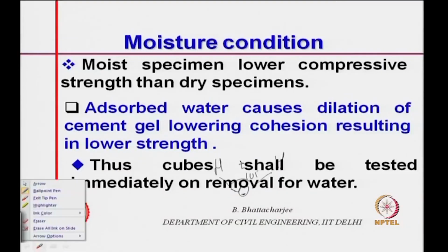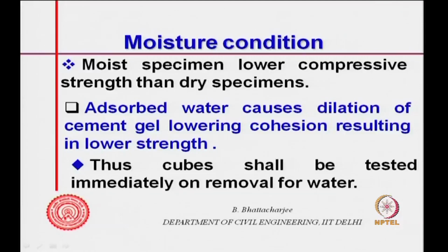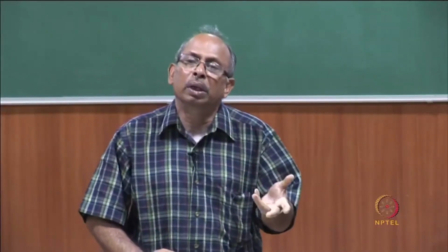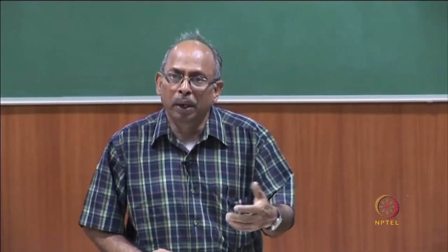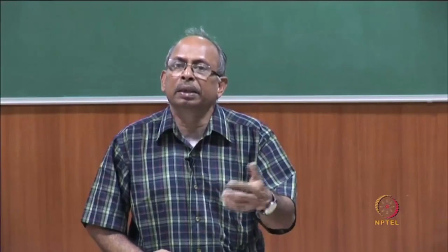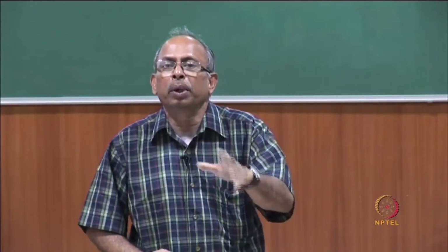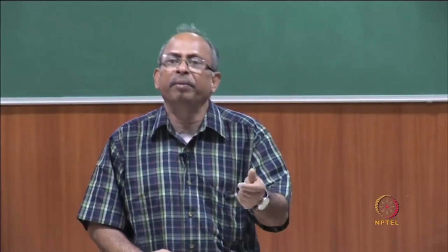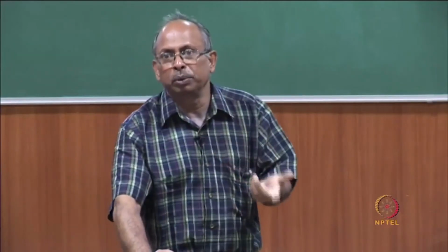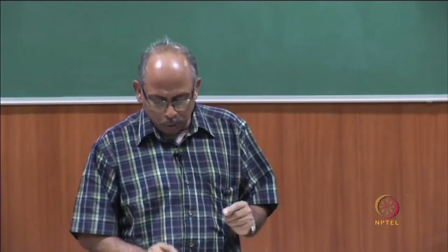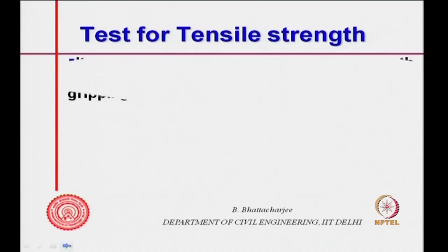Thus, cubes are to be tested at a standard moisture condition. You have a saturated surface dry situation, and the code tells you within how much time you should wipe off the surface and then test it, how long it may be exposed, and within how much time you should actually be testing. So, moisture condition is an important issue.